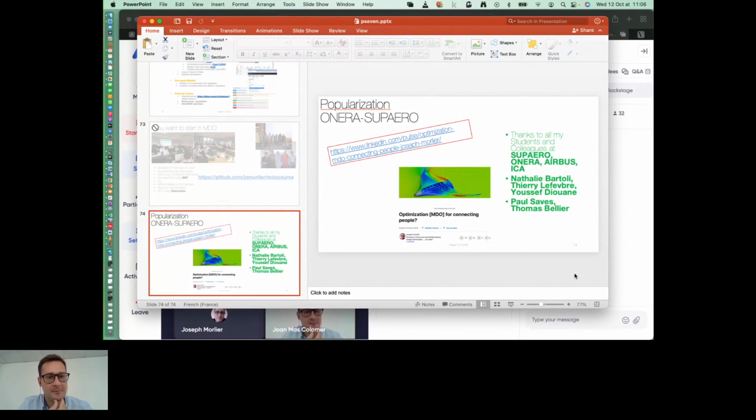if you have your simulation tool with a gradient available, and if you have HPC, you can definitely use a gradient-based optimizer, do some multi-start, and you will have a lot of computation. What is interesting with Bayesian optimization is that you can have a trade-off between the learning part, so which surrogate, and exploration, and the exploitation part. What we commonly do is start with Bayesian optimization to obtain a certain zone in the design variable domain, and then start gradient-based optimization with this initial point.